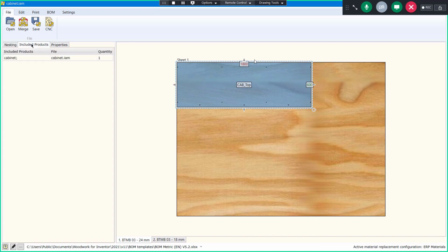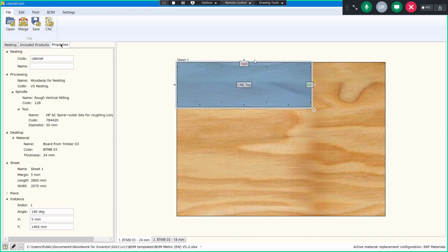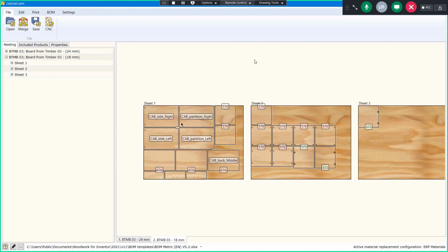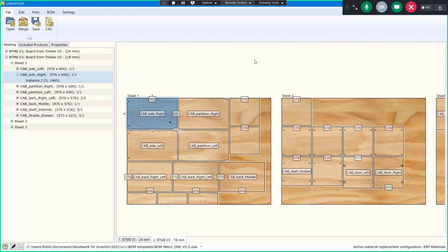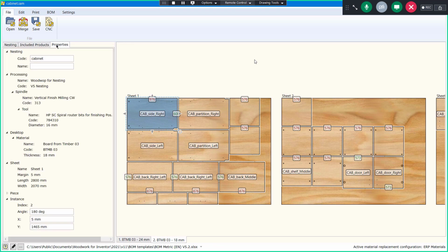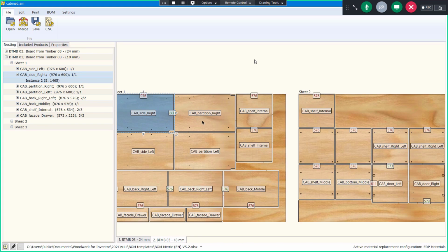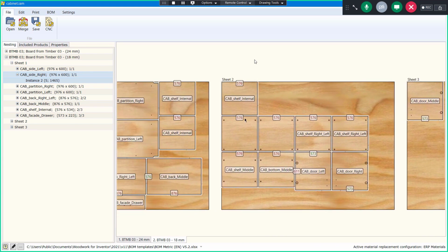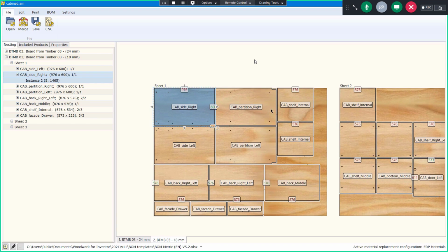There is a browser which shows the parent assembly information, the information about the part, and about the tooling, and here we can see the final layout of our assembly. Each part has size information and a label with the code of the part. So we can get all the information from the layout side, or see it in the browser as well: names with their codes and the sizes of the workpieces.